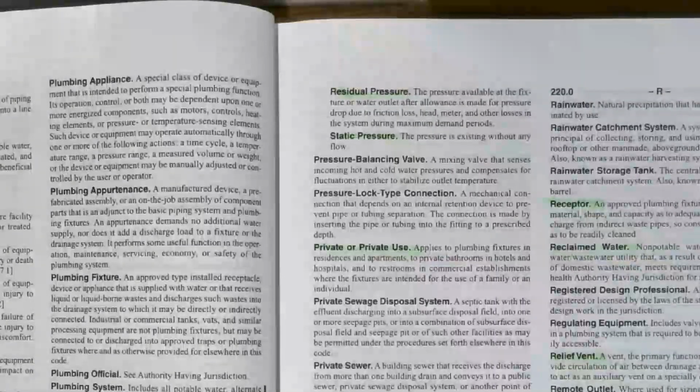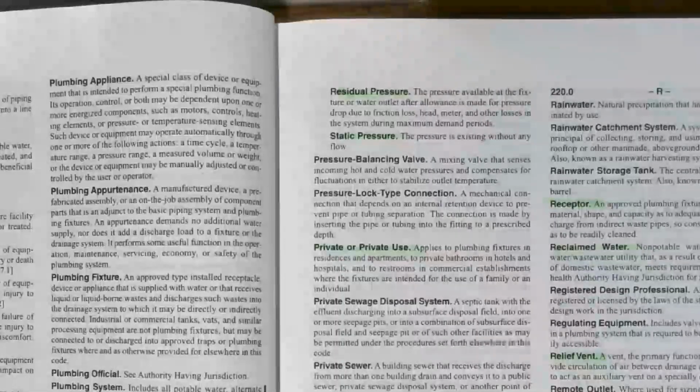Let's say your furthest fixture at the top is 60 feet up in the air, and we'll do everything based on chapter 6 of the code, which is water. We'll decrease our pressure 0.5 pound per foot of elevation. Okay, so at 60 feet, I'm dropping half a pound of pressure, so that means I dropped 30 pounds of pressure just to get up to the top fixture. So 80 minus 30 is 50.